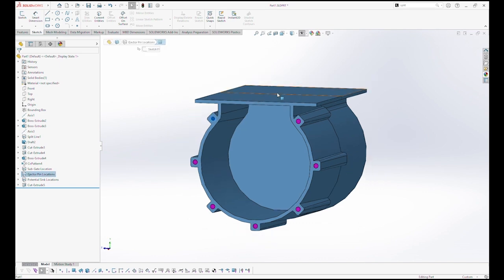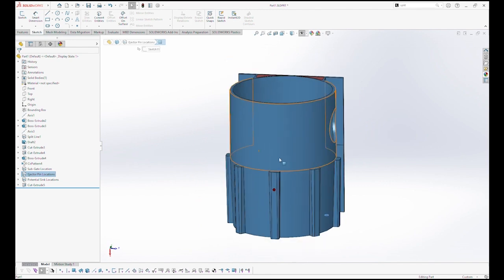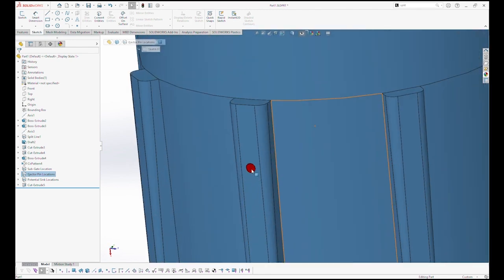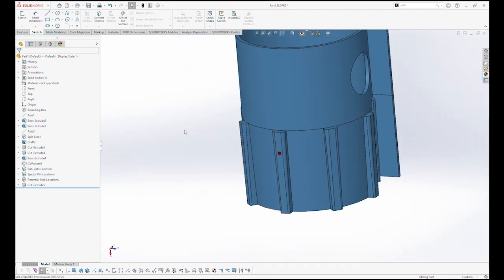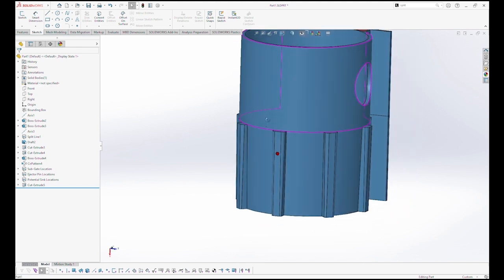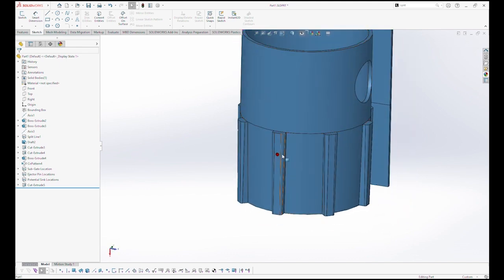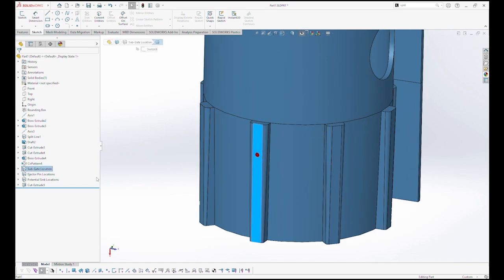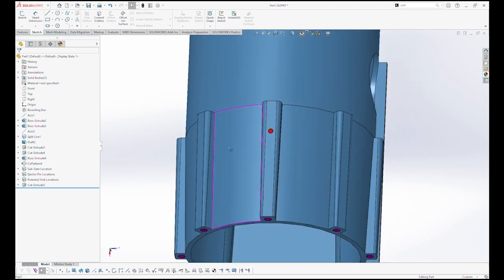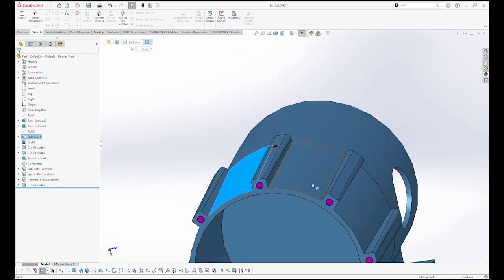And then also, additionally, as we saw in the animation, we found a location that was important for us relative to the gate. And two things about this location. Number one, this is a flat surface that we're going into. I know when you look at this surface and this surface, it looks flat as well, but it's actually a drafted radius.